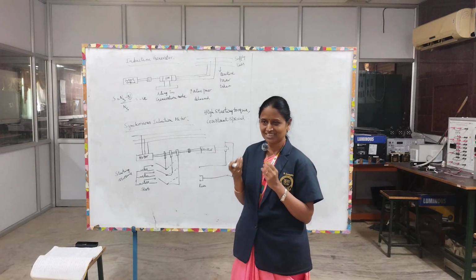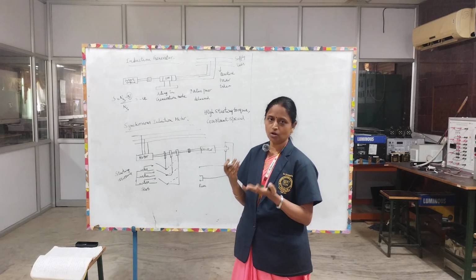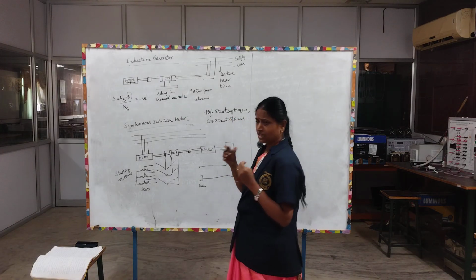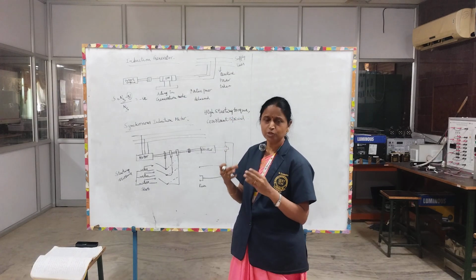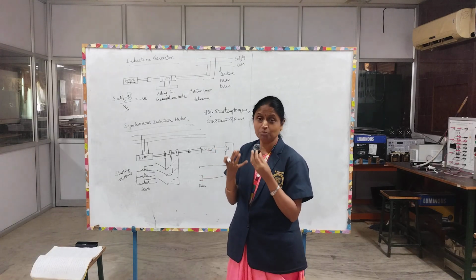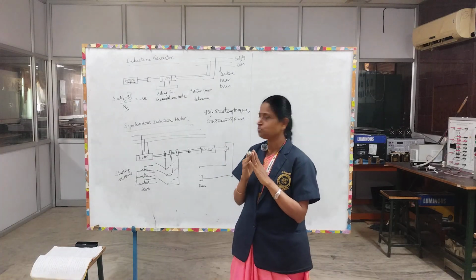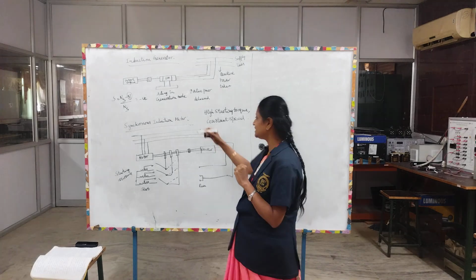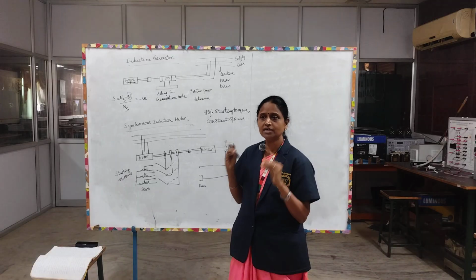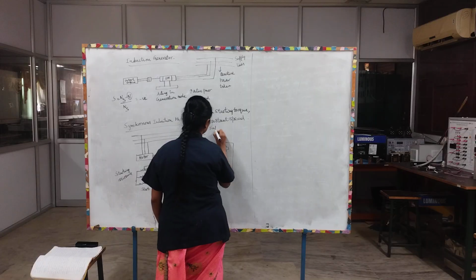Starting torque is nothing but the torque developed by the induction motor at the time of starting. We know what a torque is: it is the turning or twisting moment. High starting torque is required initially to start the motor under load, that is, to overcome its inertia we require high starting torque. So this synchronous induction motor combines the features of both the synchronous machine as well as the induction machine. That is a very important thing in the case of the synchronous induction motor. Here we are having supply lines.